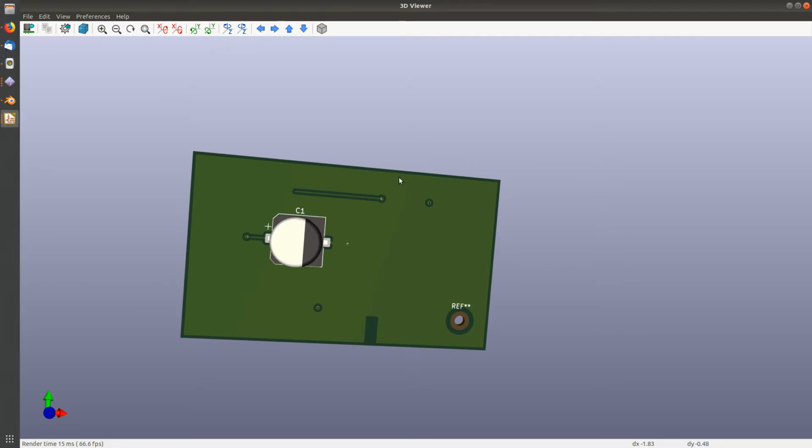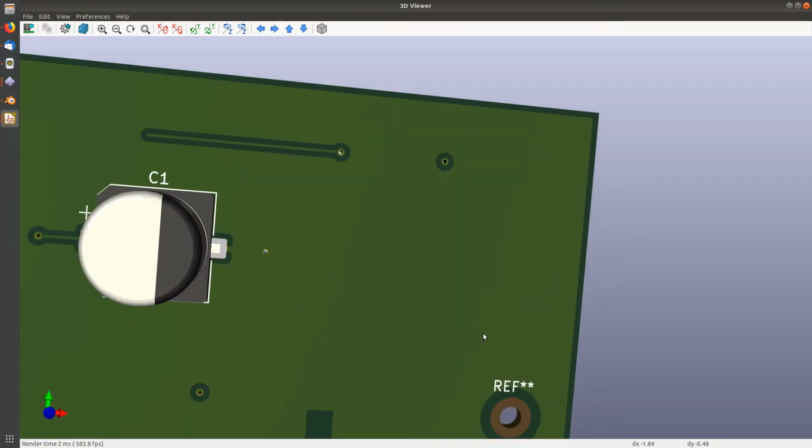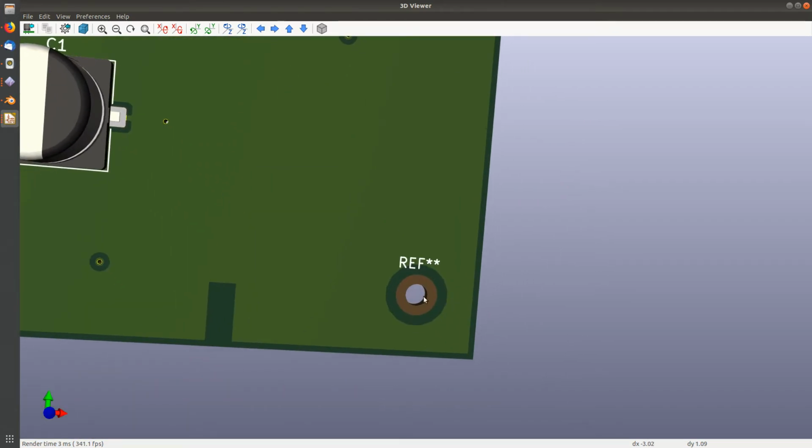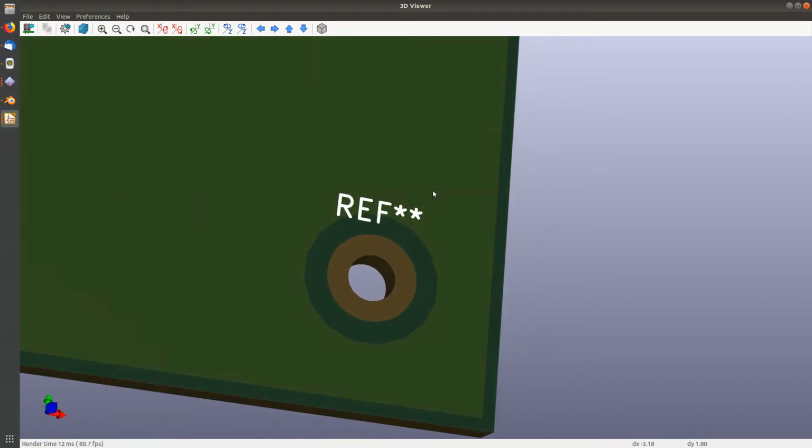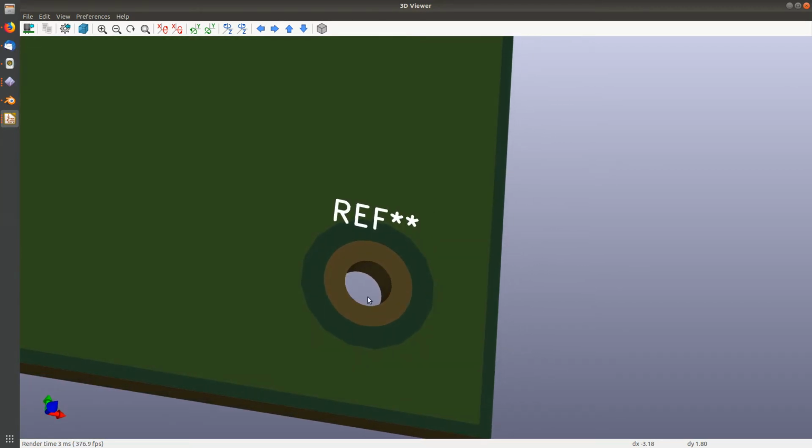If you look very close at the mounting hole, you'll see this exact pattern, although my demonstration, again, is an exaggeration of their pattern. You'll see a non-plated through hole. You'll see bare PC board fiberglass. You'll see the solder mask, and a little bit of a gap in there, and then you'll see their ground plane, their filled region around and underneath this thing, right?